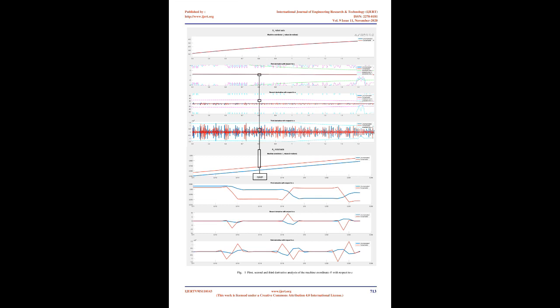The first four diagrams show the displacement and its derivatives with respect to S. Taking a wider range of the total vector displacement S allows an analysis of the changes of the appropriate functions, how frequently such changes happen, whether there are any unwanted fluctuations, and whether there is some significant difference between compensated and uncompensated values. If there are some violations of the limitations raised out of velocity, acceleration, and jerk of the robot's first axis, they could be noticed as well.